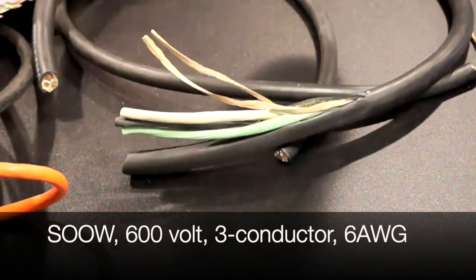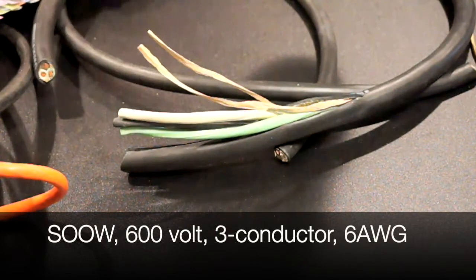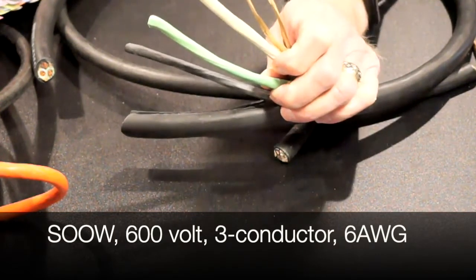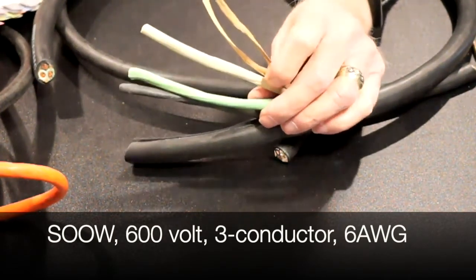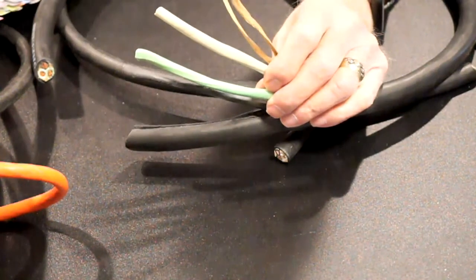So if I continue reading on the outer jacket, it says 3 conductor, 6 AWG, then it says SOOW, 600 volts. So when I look in table 400.4 on my properties for my flexible cords and cables, for SOOW, the first thing it tells me is that this is a hard service cord, which means that it has the S.